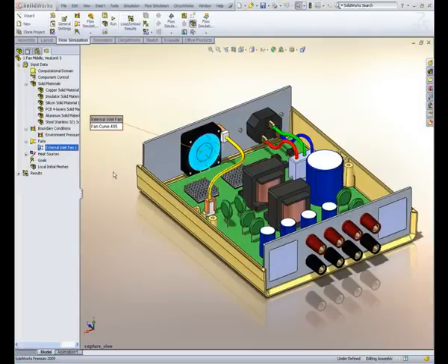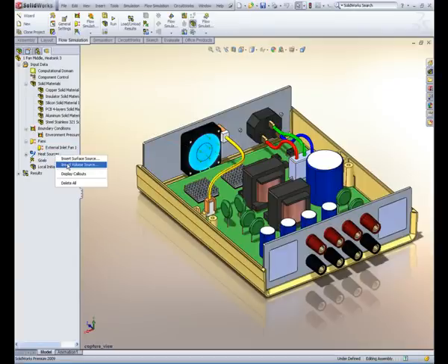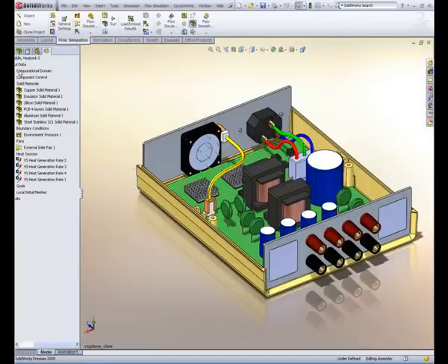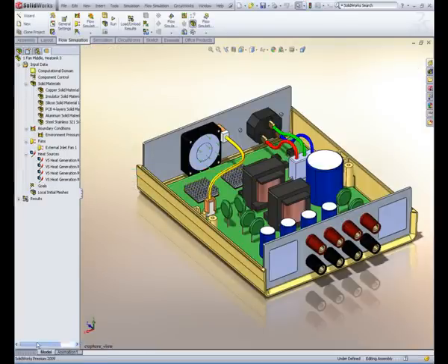Now, remembering that the reason for a fan is to help remove heat from the enclosure, we must ensure that we define the heat emitting component in our model. For example, we can insert a volume source to make the CPUs generate 10 watts of electrical power. Similarly, we have set up heat sources for the large capacitor, medium capacitors and the transformers.